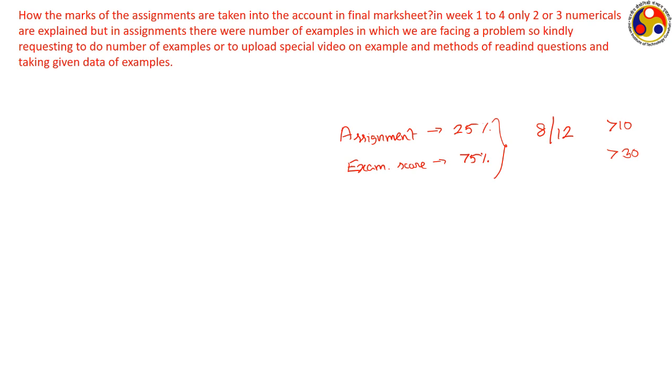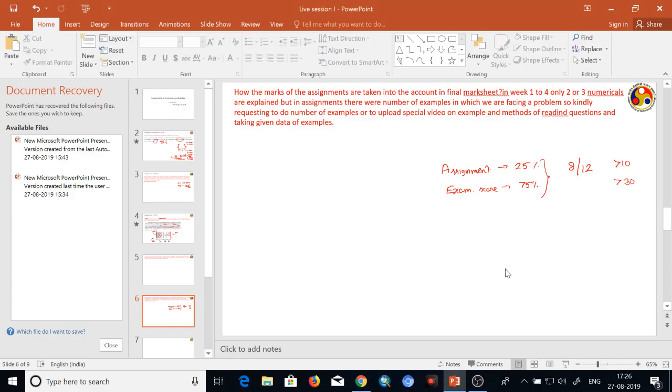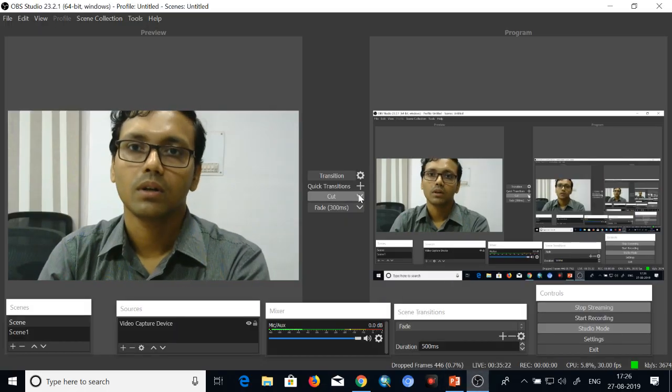As we have seen, if you talk about a hollow cylinder which is wrapped by some layer of insulation, and then as the thickness of insulation increases, let us neglect the thickness of the insulating material itself, and just talk about the thickness of the insulating material. Now as the thickness of insulation increases, the corresponding conduction resistance increases, because the conduction resistance is proportional to the thickness of insulation. Whereas for convection, the convective resistance is dependent on the surface area, because you know that convective resistance is 1 upon hA.